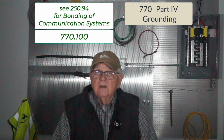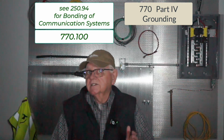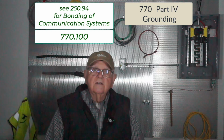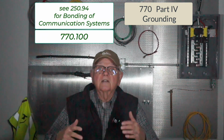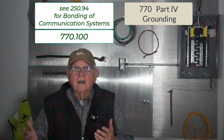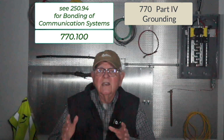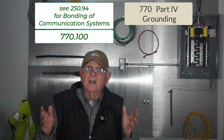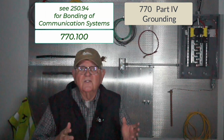Also, some other things that we're going to find in Part 5, it's specifically actually in 770.100, it says, you know, some basic things like run my conductors in a straight line, provide for physical protection if needed. It refers me to 250.70 as to how I make my grounding and bonding connections, which we just go back to Article 250 for.